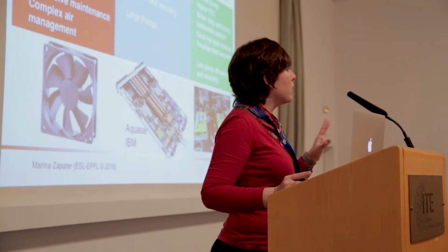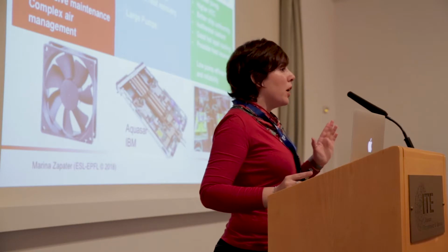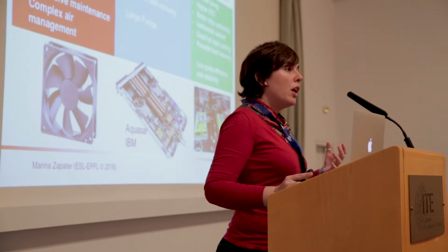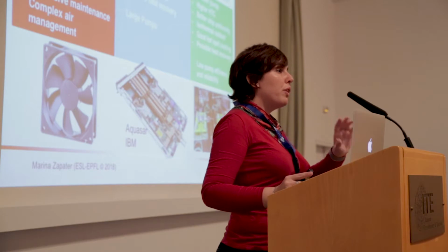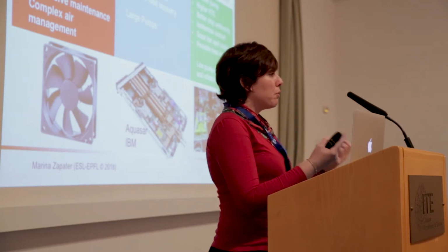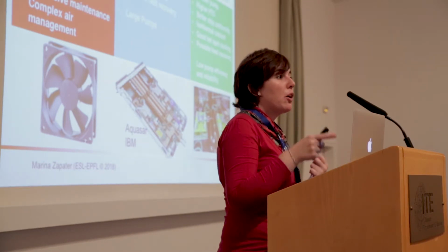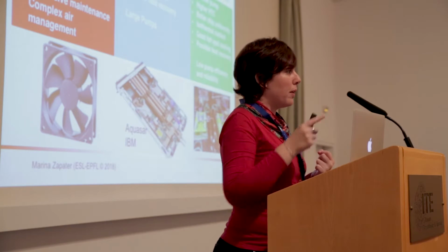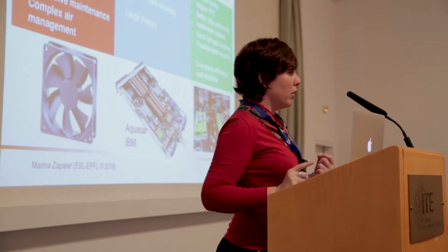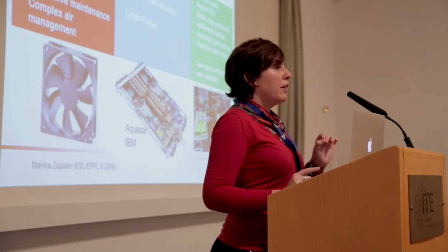Two-phase cooling is basically this: instead of simply making a refrigerant flow, what you want is for that refrigerant to evaporate. Because when you go from liquid state into vapor state, you're able to absorb a lot of heat, and we are going to absorb the heat of our processors by going into vapor and then going back into liquid. I'll tell you a bit more of this with some examples,